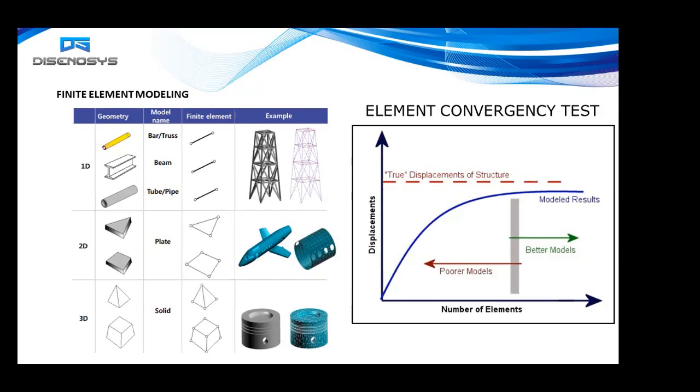Okay, so the similar 2D element can be used for that piston also, like while modeling? No, you can't use the shell element for piston. If you do that, you can get the results, but your result will not be accurate, because your piston will have a lot of profiles in it. So you can't match those profiles. If you want to match it, you have to mesh it with the higher elements. Again, your computational time will go high, but your accuracy also not much better.